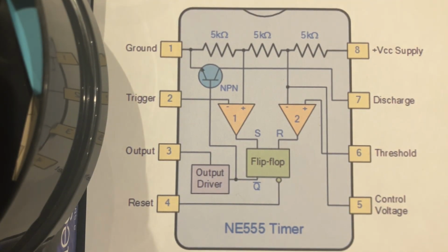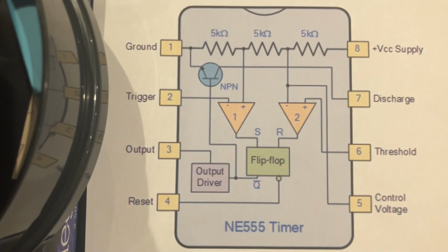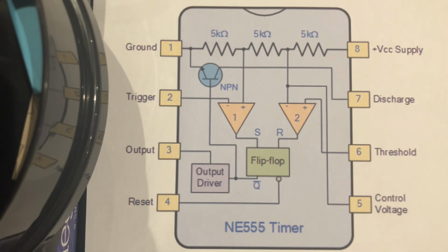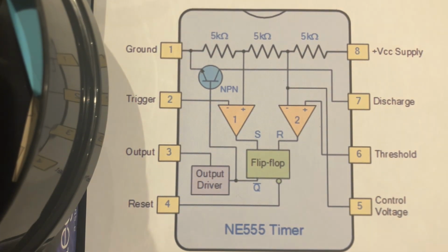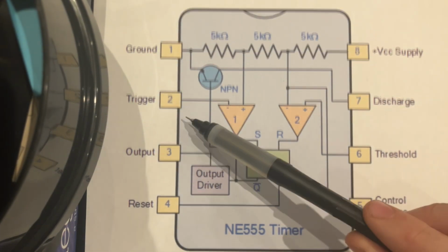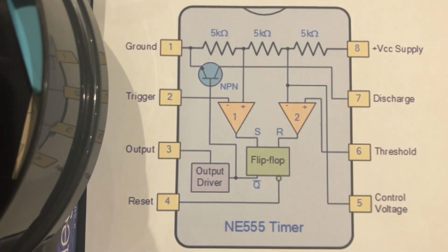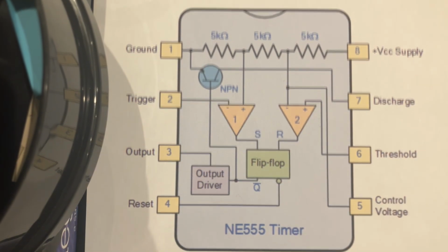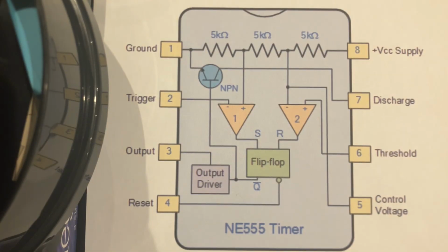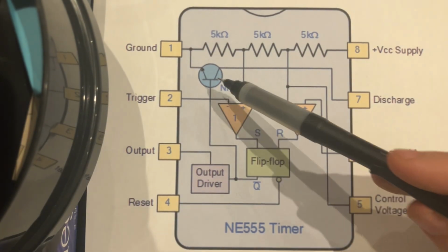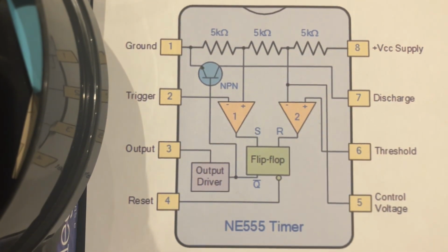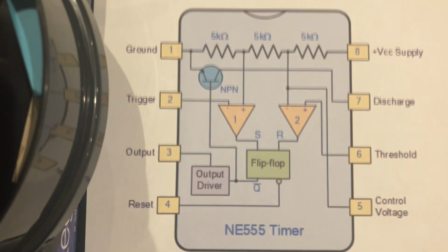The monostable 555 timer only has one stable state. In the stable state, the timing capacitor is fully discharged. Pin 2 is being held high by the pull-up resistor, and the output pin 3 is low. The discharge transistor inside the chip holds the capacitor at ground while keeping the circuit stable and waiting.